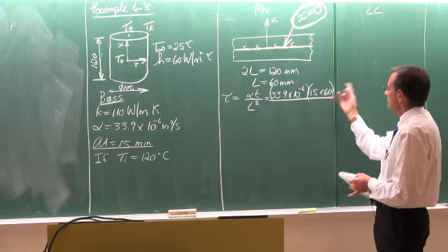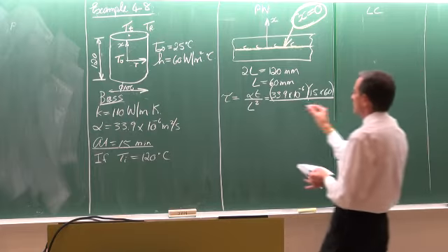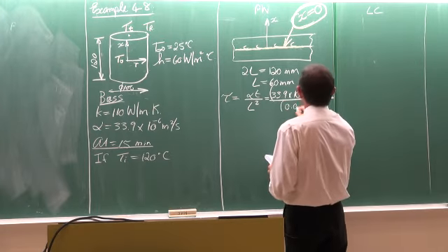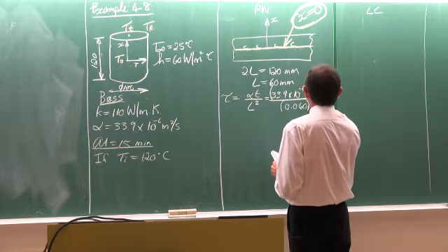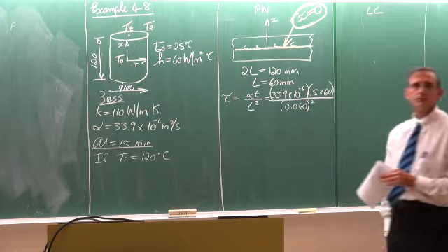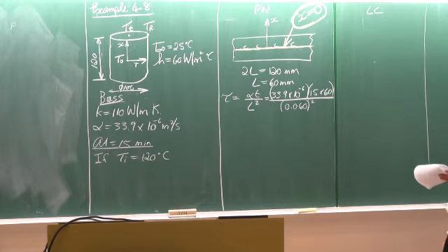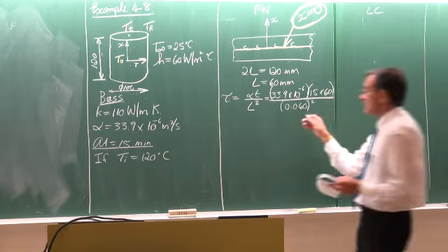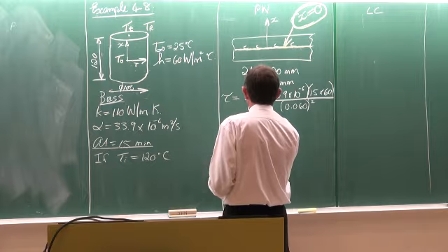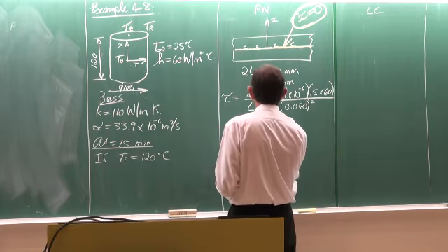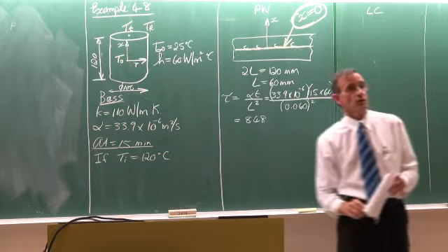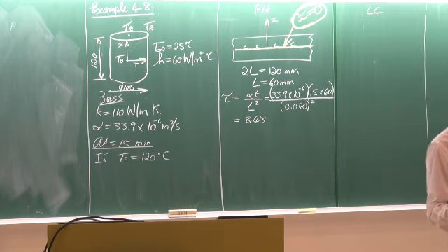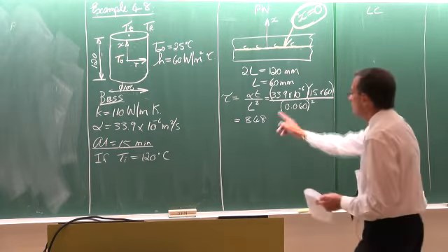So you can put in 900 or 15 multiplied by 60, doesn't matter, divided by 0.06 square, 60 millimeters. So the result is that the non-dimensionalized time is equal to 8.48. So immediately we should be very happy because it's larger than 0.2, which is good news for us.